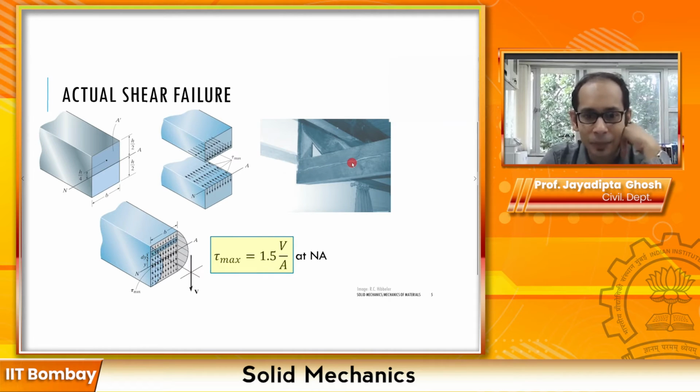And a very interesting thing to note, you see this crack, it propagates along the longitudinal axis. That also gives you that sense of complementarity that is there. At the center, the tau is the maximum, that is this tau max that you have over here, and because of complementarity, this shear propagates across this length of the beam that you have over here, as a result of which sometimes you can have a crack or a kind of failure over here.